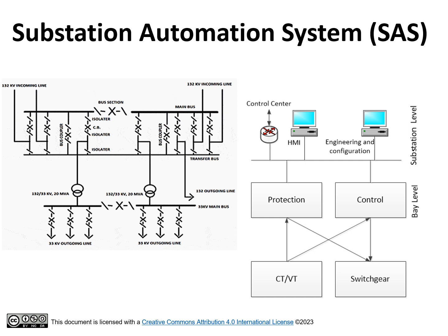The substation's automation system consists of measurement devices to measure voltage and current and feed the measurements to protection relays and control devices. Protection and control devices send control signals back to switchgear to control the operation and isolate any detected faults. Protection and control devices are connected on the substation level to coordinate the operation and perform interlocking functions. Coordination and interlocking are necessary to ensure correct operation and sequence safety.